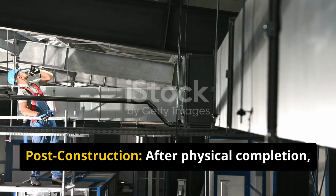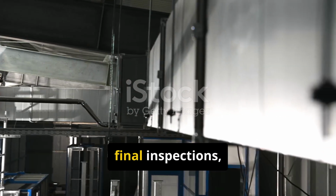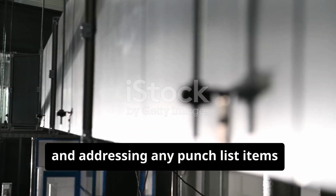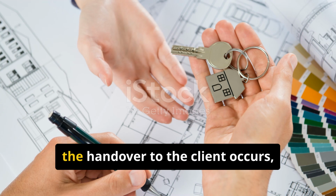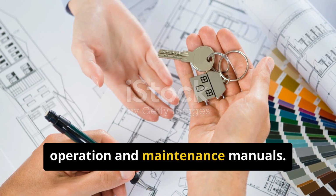5. Post-construction. After physical completion, this phase includes commissioning of systems, final inspections, obtaining occupancy permits, and addressing any punch list items, minor deficiencies identified during walkthroughs. Finally, the handover to the client occurs, along with as-built drawings and operation and maintenance manuals.